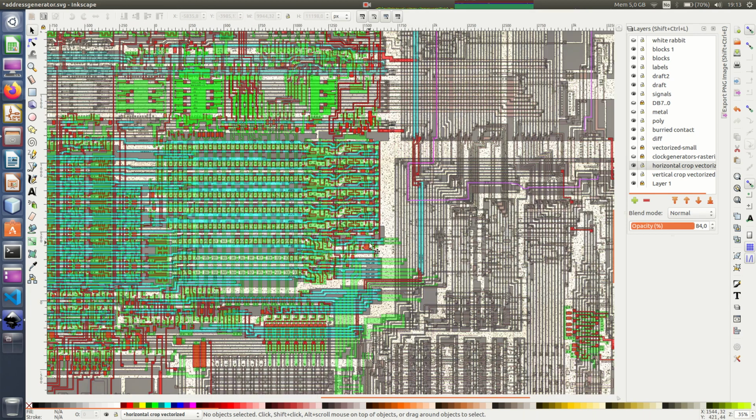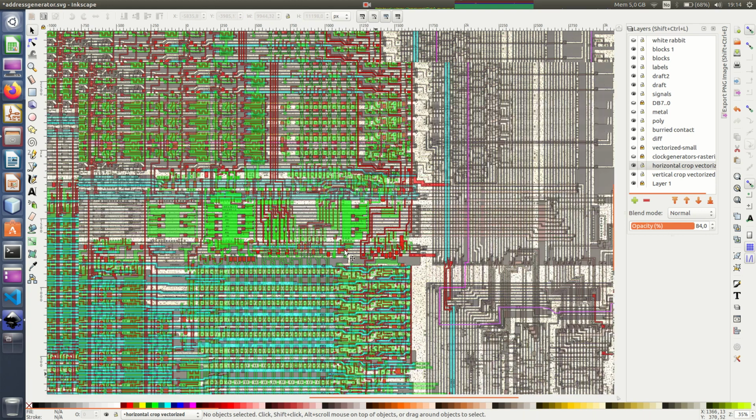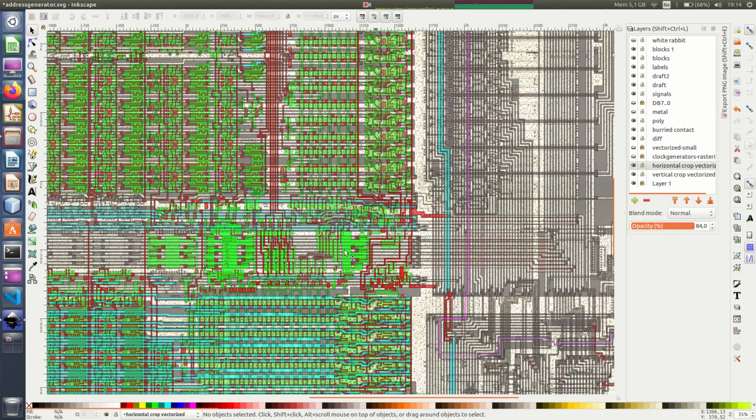So when you're dealing with synchronous logic, you don't want things to just happen whenever they happen. You want them to be synchronized. You want the state to change at the correct moment. That means you prepare the state so it's a bit glitchy and stuff happens, and then boom, you put the value out, and then it's rock solid for the next state, which is when it matters. When it's changing, it doesn't matter so much, but when it's ready, it should be ready. So that's why you have a synchronous counter, I think. That's my take on it anyway.